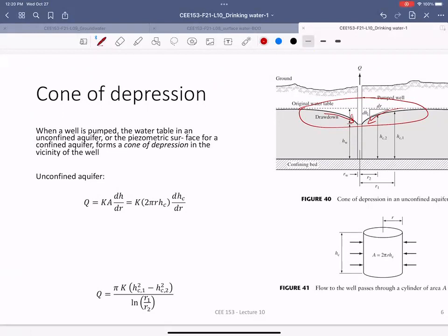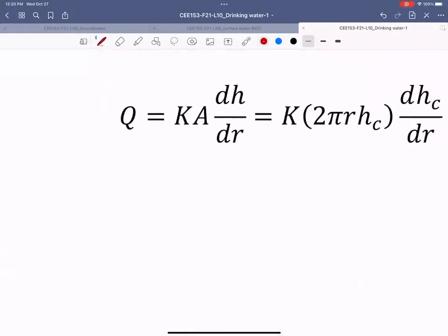So that's the area where you can get most of the water from. How far is it going to be? That radius will determine how much capture zone we will have. So how do you determine that radius of the capture zone? Based on Darcy's law. As you see over here, we start with Darcy's law. Q is the flow rate, the flow rate in that extraction well.